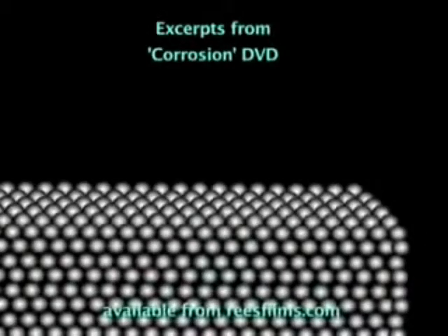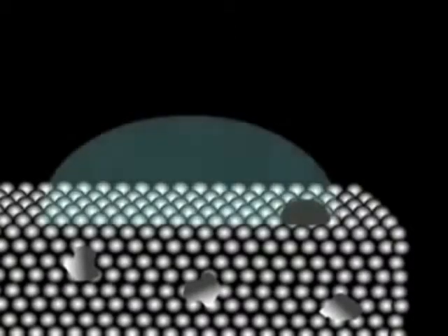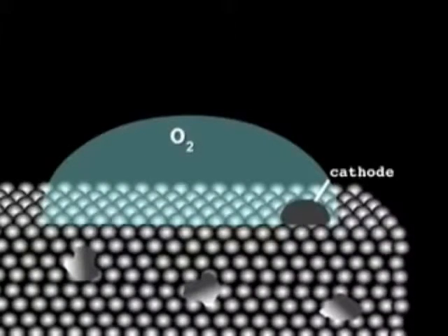We'd see that a steel object is made up of a lattice of iron atoms, with tiny lumps of carbon dotted through the lattice. Some of these will be exposed at the surface. If a lump is in contact with water, it will have contact not just with water molecules, but also dissolved salts and dissolved oxygen from the air. What we have here is a kind of natural galvanic cell. The carbon acts as an electrode because it provides a ready location for electron transfer.